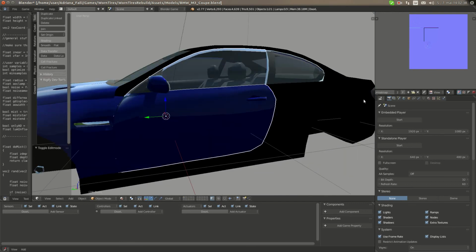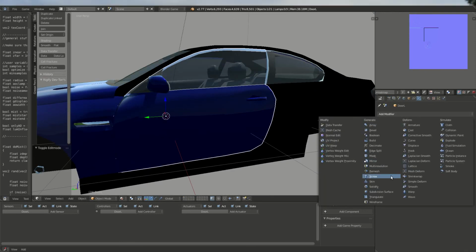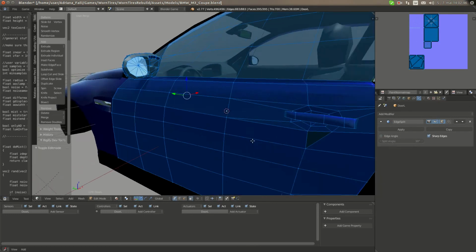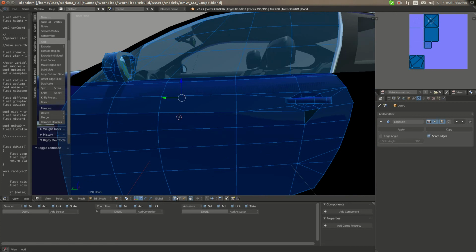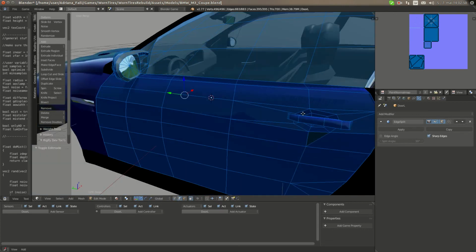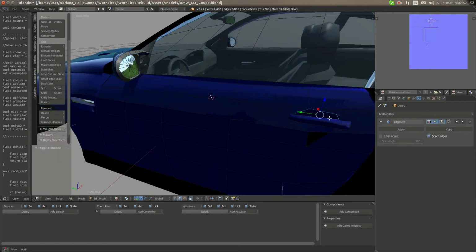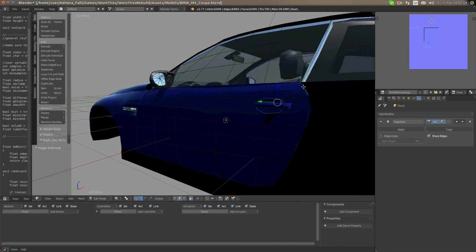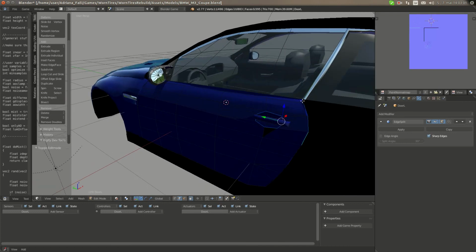Okay. And here as well we'll do the edge split modifier, which will only apply for those edges, but we get a bit of breakdown because we've lost all of the sharps for some reason. For some mysterious reason, we lost anything that was sharp. It became soft.